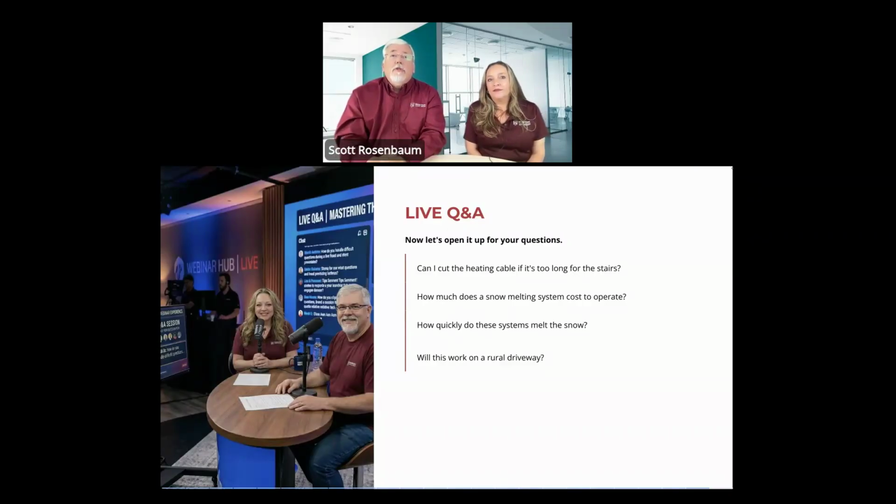Do you have to install the slab sensors or can you just control it manually? Well, if you're in a state that isn't New York or New Jersey or Vermont or Colorado or any of those other states that require you to monitor the temperature of the slab, what that means is usually, in a nutshell, those states are looking for any time that the temperature of the slab goes above 50 or some other arbitrary number around 50, the system should shut off automatically.